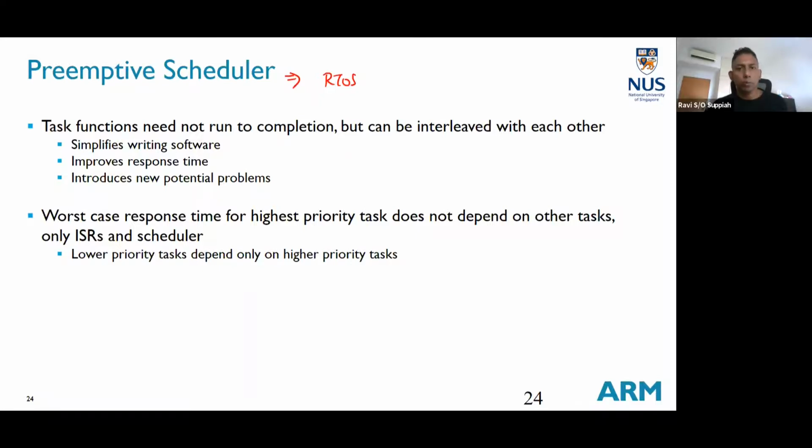When you run your system on an RTOS, or you basically load your controller with the RTOS, you are not only having this capability of preemptive scheduling, you are also bringing together all the features that you need to make sure that you can develop multi-threaded code while taking into account all these challenges that you will also have to face. So that is the idea of using an RTOS.